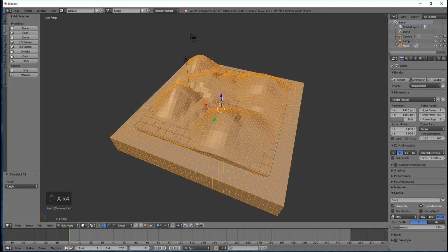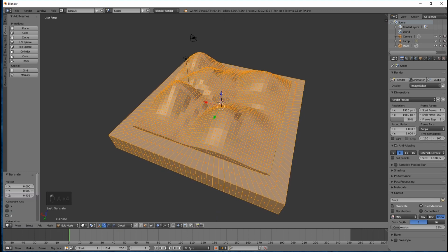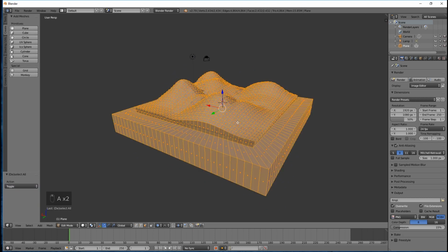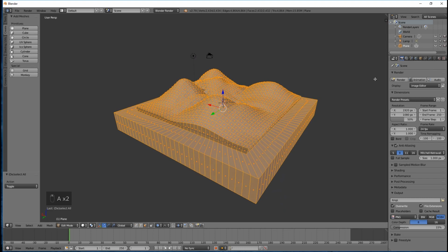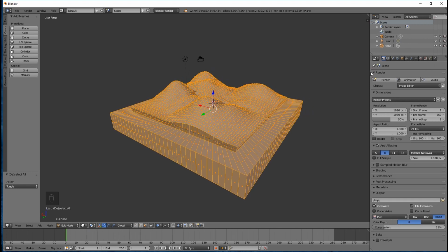And in fact, I'm just aware that we can see that guide at the bottom there. So I'm going to move the island up a little bit. There we go. So I'm going to press A to select the whole model, and on the right hand side of your screen you have this fairly complicated looking toolbar, but rarely do you have to use very much of it. It might be that you can't see all of these buttons in this row here. So if you can't, or you don't know if you can, just grab the left hand edge of this panel on the right, click and drag it in a bit, and then you'll be able to see this whole row of buttons here.